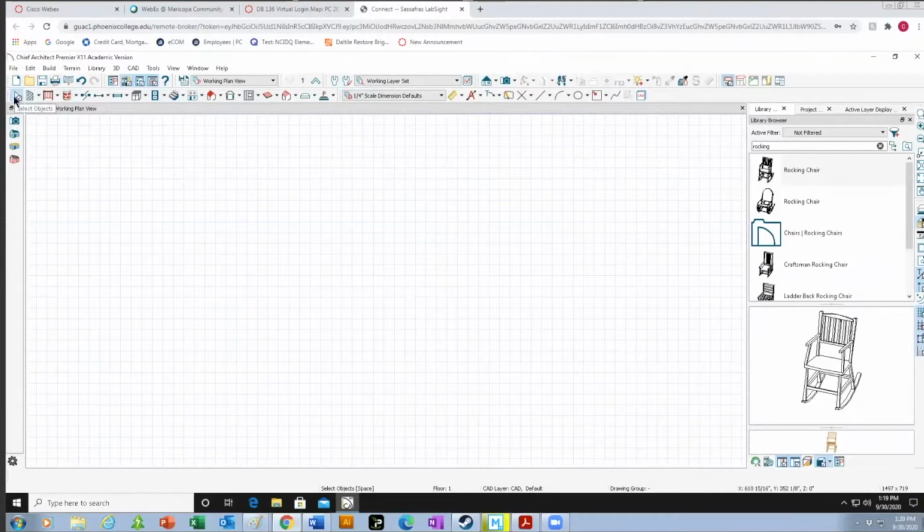Very important. Then we have the drop down for all your walls. So we have exterior walls, straight walls, foundation walls, pony walls, glass walls, straight half walls, room dividers, etc. These have all been set to a default, like 6 for exterior walls, 4.5 for interior walls. You can update these if you're doing something very custom, but for the most part, we just use the default.